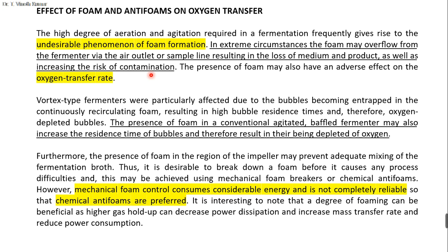The presence of foam with a conventional agitated, baffled fermenter may also increase the residence time of bubbles, and therefore result in depleted oxygen. That means for vortex type fermenters this is a problem. Also, mechanical foam control consumes considerable energy, and it is not completely reliable.